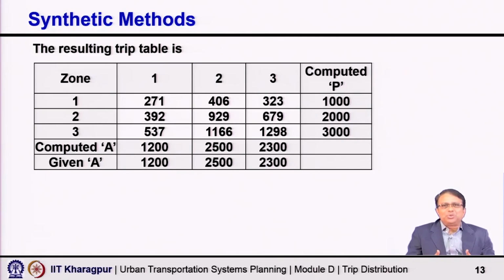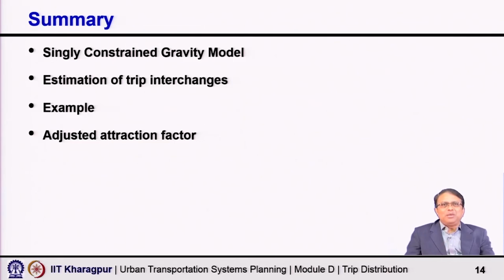You are not going to do hand calculation, because any reasonable study area will have multiple zones, and you will all use computer. So, set your acceptable error limit, accordingly let it iterate and come out and give you the trip distribution when the error is within the acceptable limit. So, that is the way you can actually apply it.